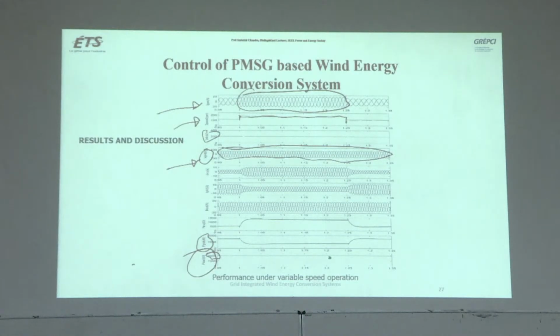And then you see the speed is increased. So the power initially generated by the inverter was 500 watt, but because the speed is increased, the power output transferred became almost 1500. So the grid will provide less power to the load. So this is what to show. The grid current earlier was this, now the grid current is reduced because the power was coming from the wind turbine. Okay, this is just to show these results.